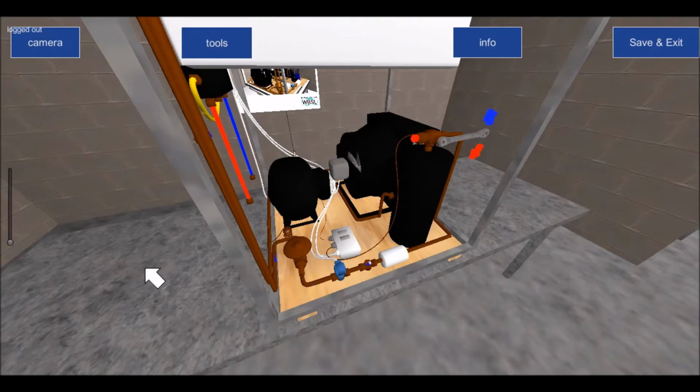Whereas when you're starting it from a low pressure, from 1.5 or 2 bar pressure, there's less drag, less overload on the actual compressor, and less chance of the compressor going out on overload.